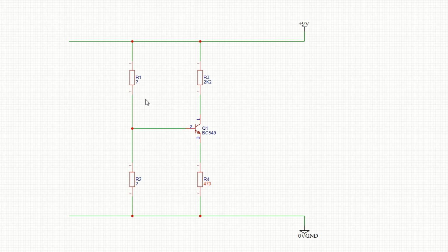So say the transistor's got a gain of at least 100. Yeah, I wouldn't go above 100 times that value for that resistor then, just as a ballpark figure. So you don't want to go above about 47k there, and you want about 5 times higher on that one to make it 1/6.